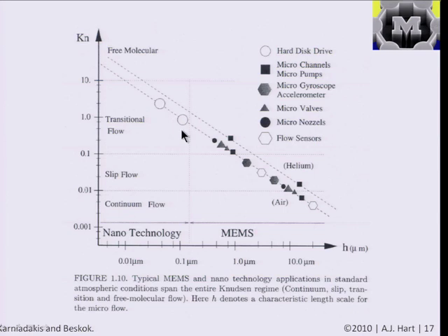So even though it's a microfabricated device, it's relying on an understanding of the dynamics of flows at very small length scales, and often requires a lot of specialized flow modeling to consider how the gas interacts with the surfaces. But the take home here is that a lot of MEMS devices and materials into the nanoscale require consideration of these interactions and consideration of slip.